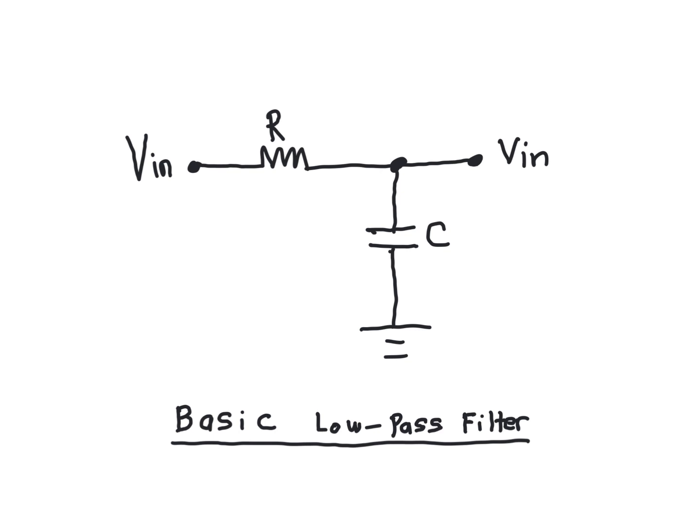The filters we're going to be working with are called active filters because it uses an op amp, and we'll talk about that. But the basic filter is composed of a series resistor and a parallel capacitor, and this should be V out. Okay, and the operation is really easy to visualize.